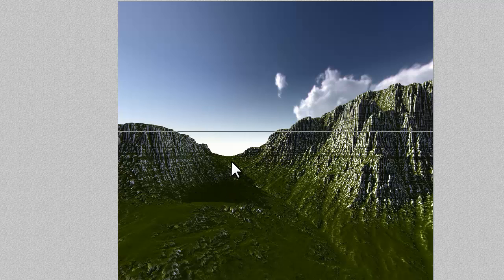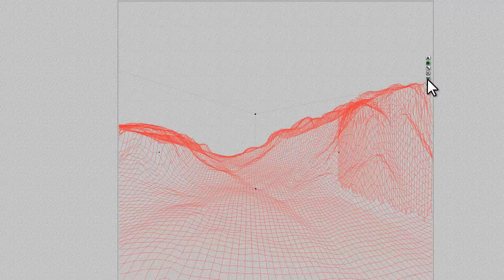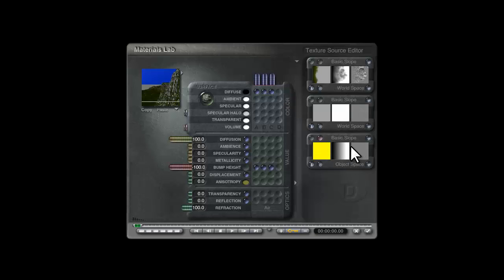Ideally, you would try and separate off the various parts, so work on one part. What you can do, if you know you're not using a channel, for example, we're not going to use anisotropy in this, is press Ctrl T down, pop everything in C, and then I can just work on one channel at a time.